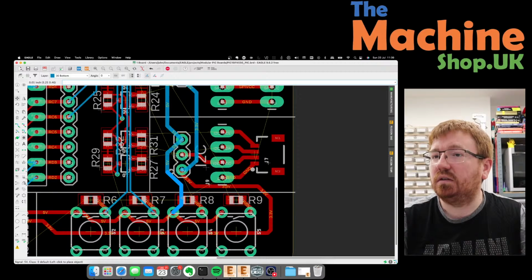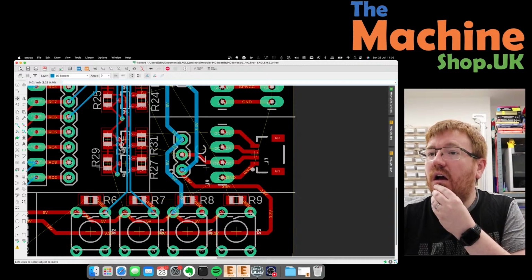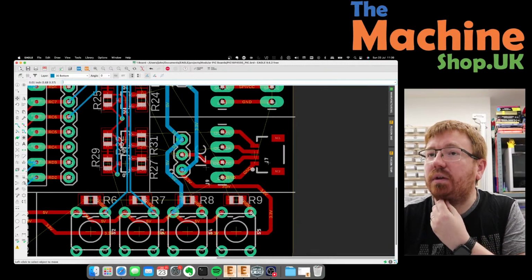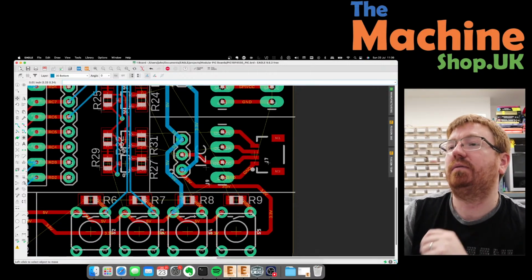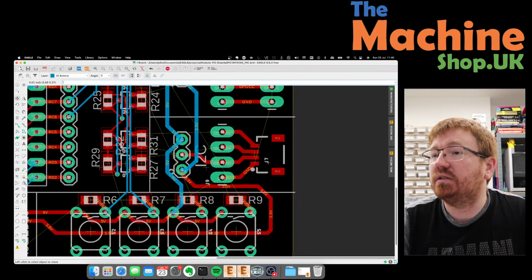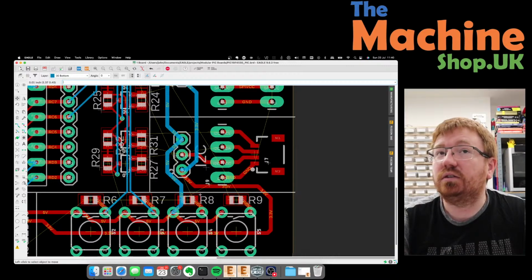Okay, fine. Now, can I get... I need to get RB5 over to there and RB4. I might be able to get RB4 to squeeze down the middle of these, but I doubt I'm going to get 4 and 5 to get to there. So can I... Might have to via it again, change to red, to the top layer, and then move into that bit. It's not pretty. What else can I do?